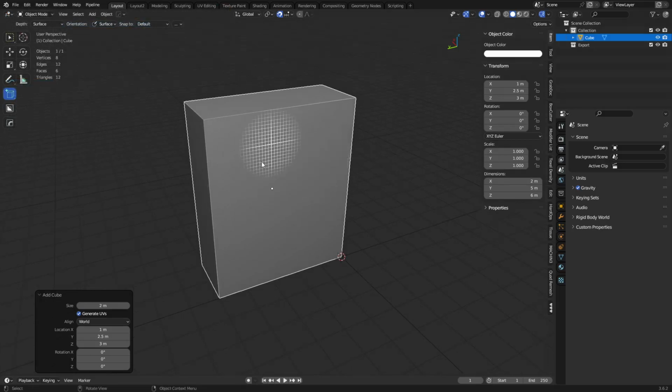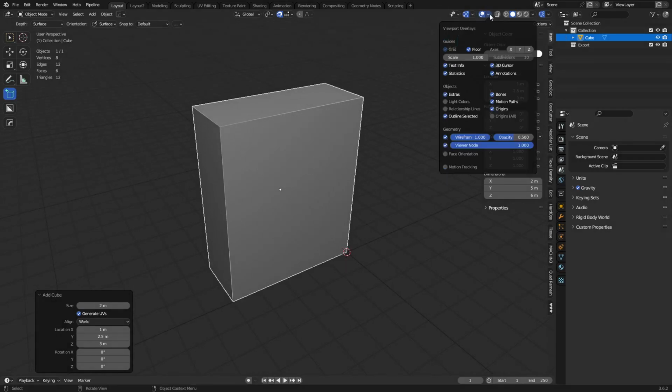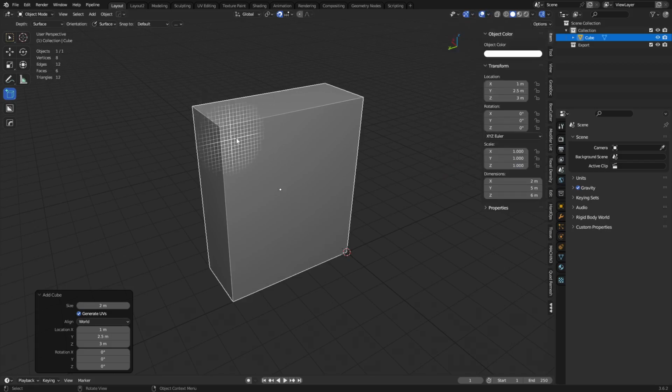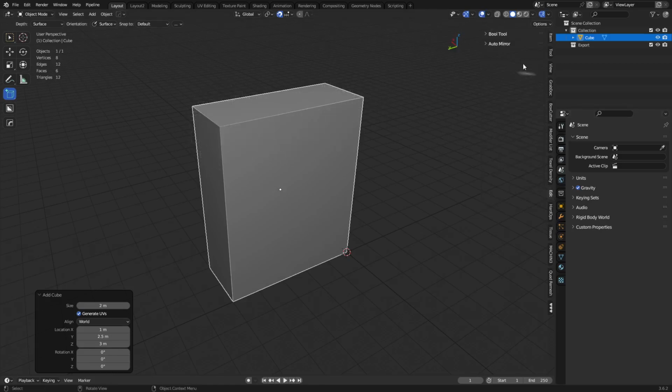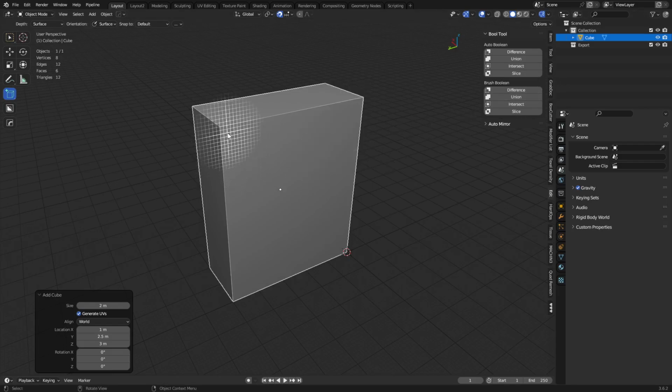But what we're going to do is use this to create cutters, basically. So we can go ahead and set our scale down lower to maybe 0.1 if we want. It's still got snapping on, right? And under the Edit menu, you'll find Bool Tools over here. Now they have shortcuts for these things, Control Shift B being another menu you can access. You can see usually your shortcuts are listed here: Shift, Control, Numpad plus, minus, all that fun stuff. But we're going to be doing brush, boolean, difference, and union. Okay. And I don't have those assigned, so I'm going to use that top right menu instead.